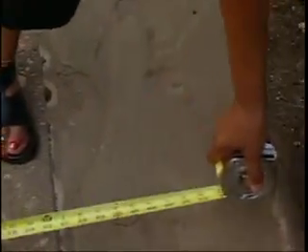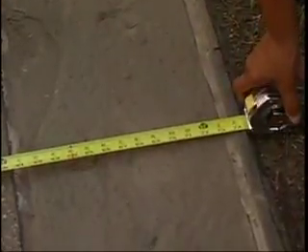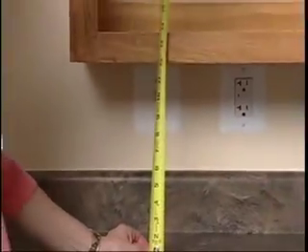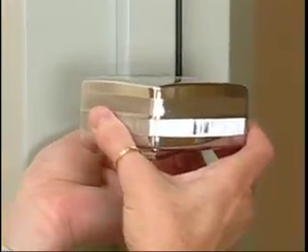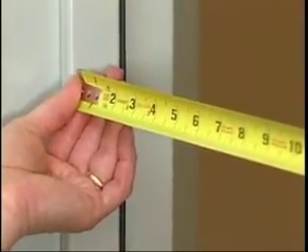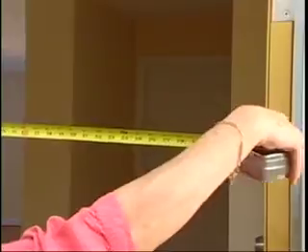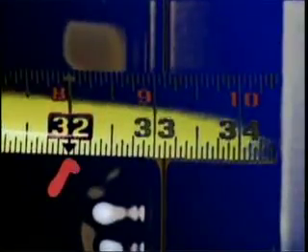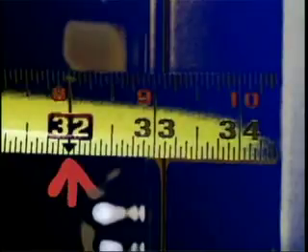We have all seen and probably used a tape measure at some time. You need to purchase a heavy-duty tape measure like the one shown here, and make sure that the locking mechanism works to avoid any injuries. To properly use the measuring tape for survey, hold the front of the tape at the point you wish to start the measurement from, and extend it to the point where you want to stop and lock the tape in place. To find the inches, read the first large number before your stop point. This will tell you the number of inches.